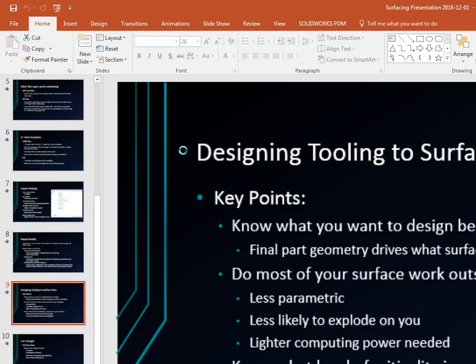Now delete hole works almost all the time when it's on one face. You can see this hole doesn't break over into another face. If it broke into the second face, it's 50-50 whether it's going to work. If it breaks onto a third face, I don't think I've ever had it patch 3 faces with a single delete hole. So, it is what it is.